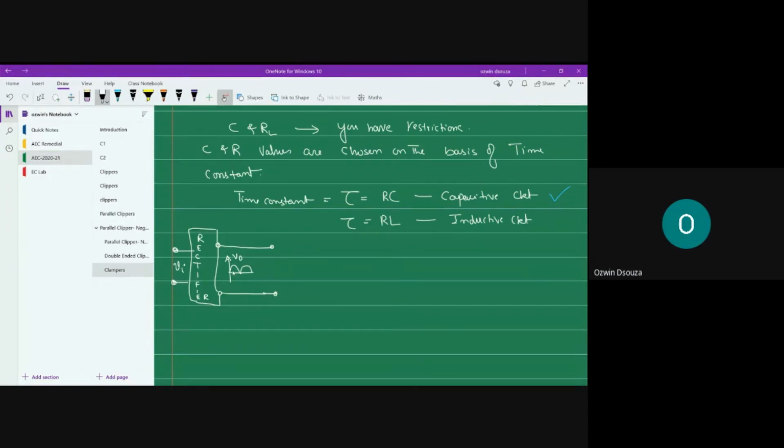So what you do in case of a rectifier is connect the rippled output to a circuit called a filter. This filter circuit consists of two major elements, a capacitor and a load resistor. Across the load, whatever output you measure will have a kind of smooth DC shape. So this is your V naught.